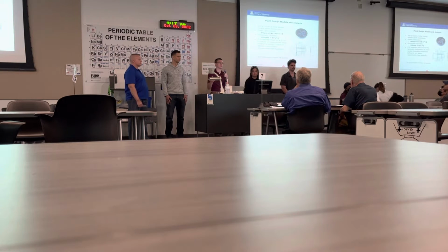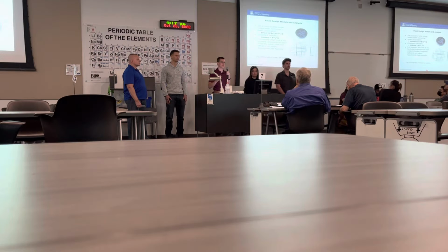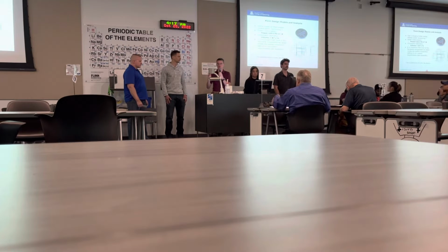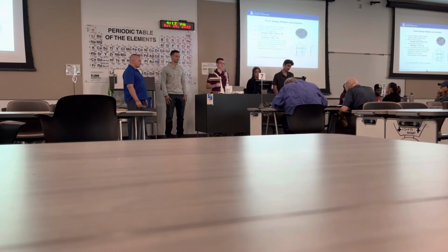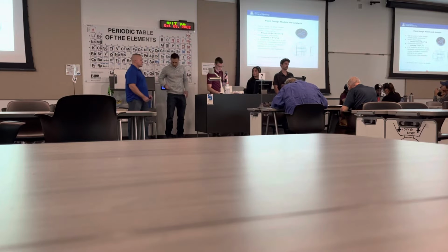And just a couple of other models worth mentioning really quickly here. Power consumption, I'll talk a little bit more about that later. And finally, component geometry. From our system requirements, we have some spatial requirements for our system, so we just have to make sure that none of the components we end up purchasing exceed those conditions. Pictured here, for example, is the OLED display. We're going to have to make sure we pick one that's small enough to fit inside our handheld device.